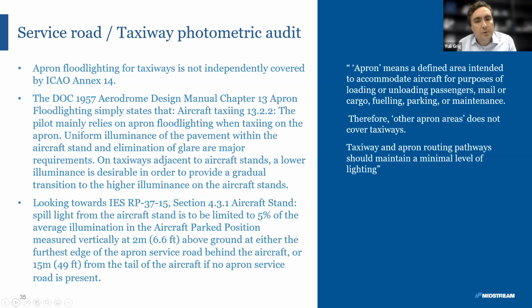Now, apron means a defined area intended to accommodate aircraft for the purposes of loading or unloading passengers, mail or cargo, fueling, parking, or maintenance. Other apron areas do not cover taxiways because you don't do any of these operations on the taxiway. So taxiways and apron routing pathways really should maintain a minimal level of lighting.